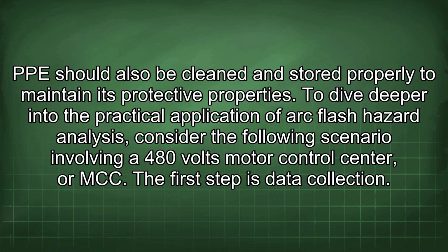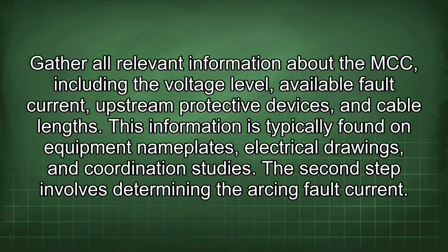To dive deeper into the practical application of arc flash hazard analysis, consider the following scenario involving a 480 volt motor control center, or MCC. The first step is data collection. Gather all relevant information about the MCC, including the voltage level, available fault current, upstream protective devices, and cable lengths. This information is typically found on equipment nameplates, electrical drawings, and coordination studies.